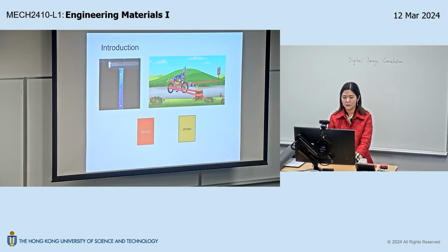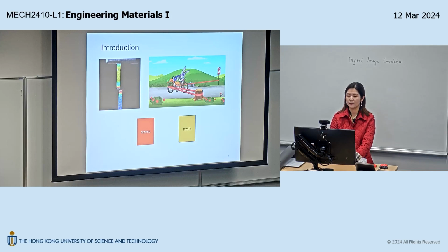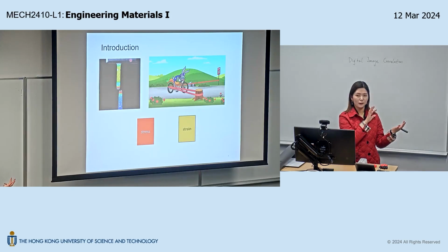So here, obviously, it first deforms, right? The color contrast, the lighter means it deforms more. Here it is still not deformed so much, and here it deforms more. As it elongates, you can see here a stress concentration, strain concentration, and break. Near the fracture surface, you'll see a maximum stress or maximum deformation occurs there that causes the fracture. So this is the formal way to characterize the mechanical property.